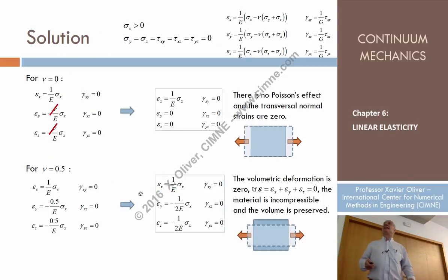That's a way to understand the role that the material properties play on the material. Look, if E is large, the strains for the same stress are small, so this elongation would be small. We say that the material is stiffer, okay? The material deforms little when we apply stress, okay?